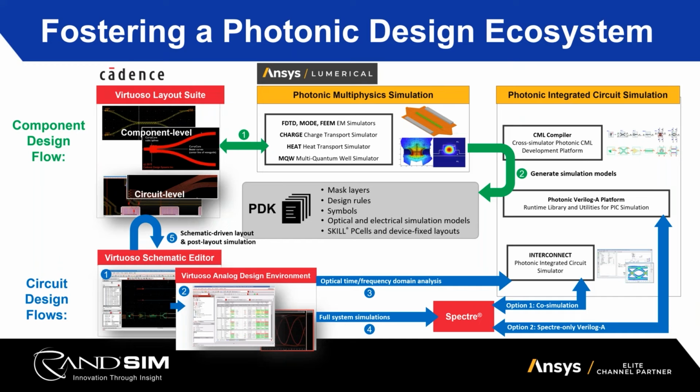And moving to the bottom, to facilitate the electronic photonic integrated circuit designs, we've integrated Lumerical's photonic circuit simulator with Cadence Virtuoso. This design environment allows users to design hierarchical integrated circuit schematics using the Virtuoso schematic editor and to perform circuit analysis through the Virtuoso ADE. From the ADE, users can perform optical time and frequency domain analysis on their photonic circuits by using INTERCONNECT as the engine.